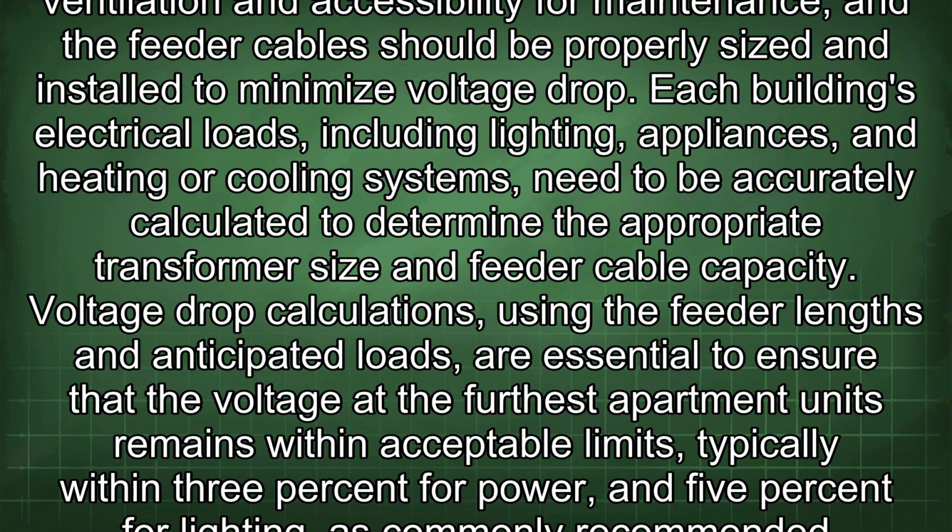Each building's electrical loads, including lighting, appliances, and heating or cooling systems, need to be accurately calculated to determine the appropriate transformer size and feeder cable capacity.